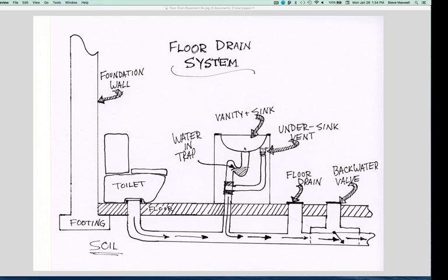The rush of the toilet water is also going to cause a kind of glug glug sound as it tries to suck the water out of the trap. I should mention too that this isn't just a function of toilets. This is anything that empties into a drain. When that section of water is flowing down here and there's no other water behind it, it creates a powerful suction. So this could be a bathtub or another sink or a toilet like you see here.